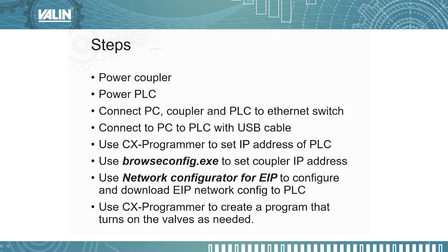I tried to go through the steps that you would use to configure this, and I put the first two steps up here. They're just, if you're teaching someone to make a peanut butter and jelly sandwich, you don't want to forget to tell them to take the lid off. So, of course, power up the coupler and power up the PLC. And notice on the coupler that there are two power connections in the same connector. One is for the coupler itself, and one is for the I/O or the valves that are connected to the coupler. So valve and I/O power, and then coupler power.